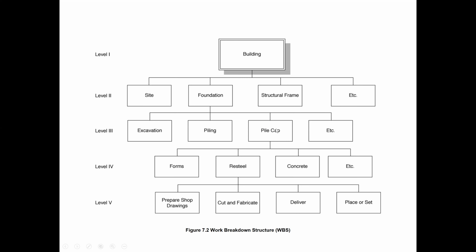Now see the pile cap. Pile cap, further how we fix the formwork, we fix the reinforcement, and then we cast the concrete for the foundation. Okay, it's a pile cap for the bridge column, bridge pier. So we have a pier column. Under the column there is a pile cap. Below the pile cap there is a piling work.